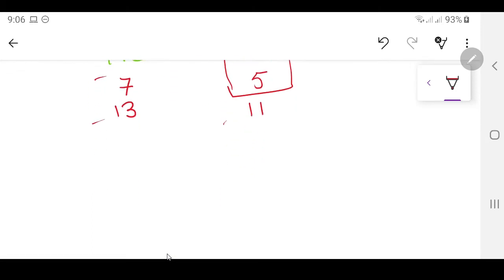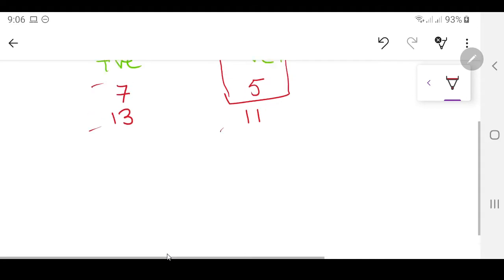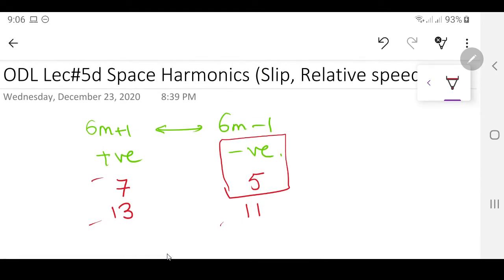When we are talking about the slip, the first important thing is that you have to have harmonics in the stator. Those harmonics will be flowing inside the stator with their own number of poles, and the speed will be different, certainly depending on ns divided by the number of the harmonic, with a positive or negative sign depicting whether it is moving in the positive or negative direction, as shown here. Then these harmonics are going to induce an EMF inside the rotor, and the rotor and stator fluxes, or MMFs, will move with the same speed.